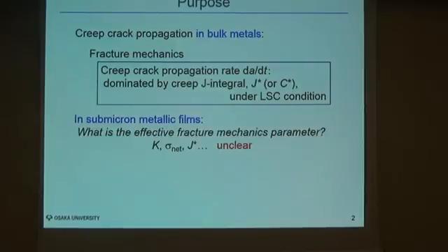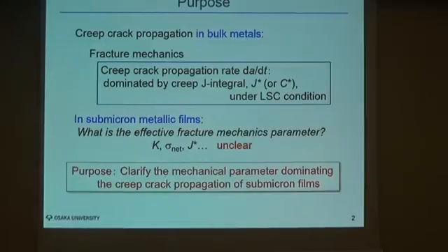However, my question is, in submicron thick, very thin films, what is the effective fracture mechanics parameter of creep crack propagation? As far as I know, this is still an open question. So the purpose of the study is to clarify the effective mechanical parameter dominating the creep crack propagation of submicron films.